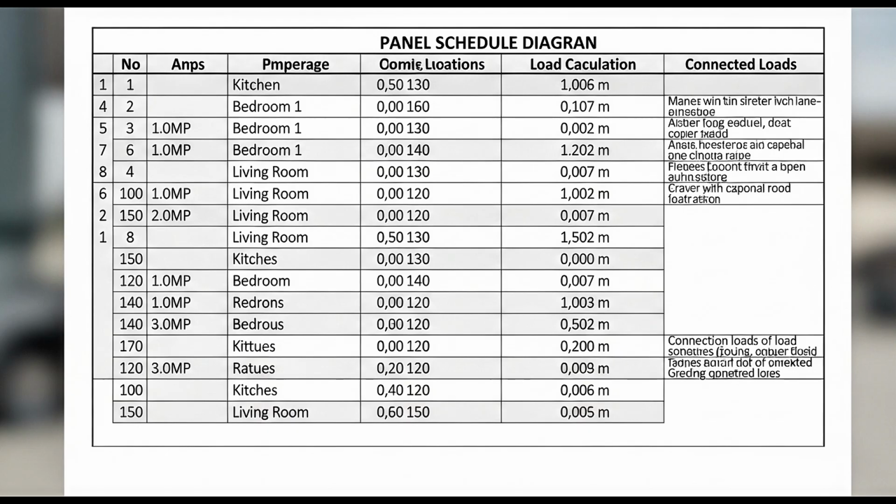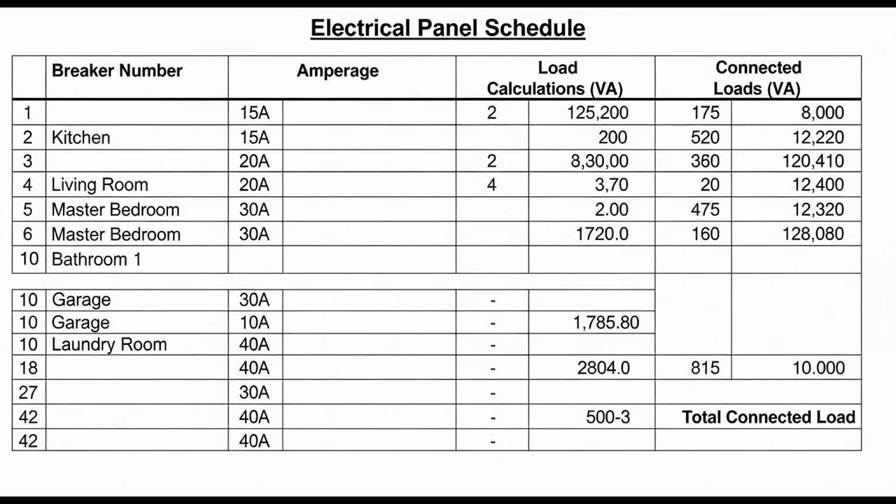When a panel is consistently loaded near its capacity, breakers wear out, connections loosen from thermal cycling, and fire risks increase. If your panel is warm to the touch, makes buzzing sounds, or has breakers that trip frequently, these are warning signs requiring professional evaluation.